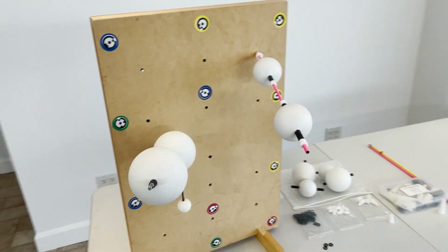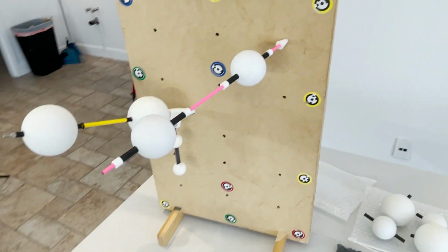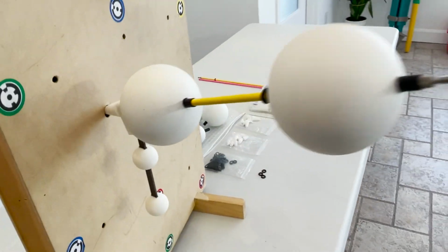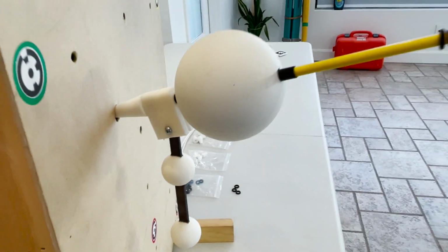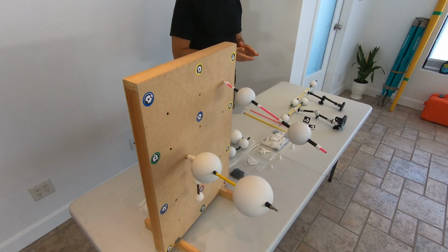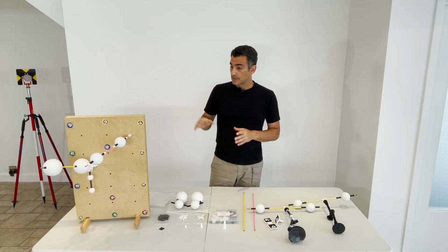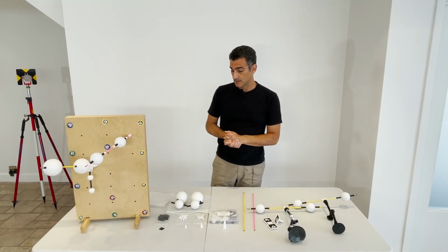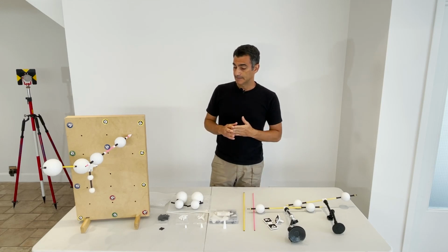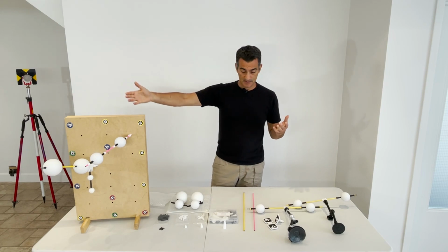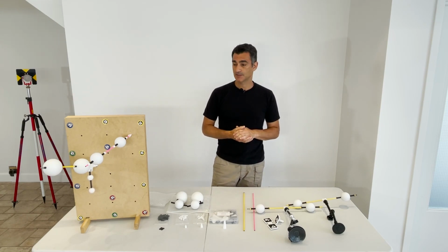And once it levels off in the software, as I just talked about picking spheres, I can pick these 2 spheres and tell it which way is up. So it's basically a special type of plumb bob that gives me an up direction. So that's basically the photogrammetry way to use rods and spheres and different types of targets.